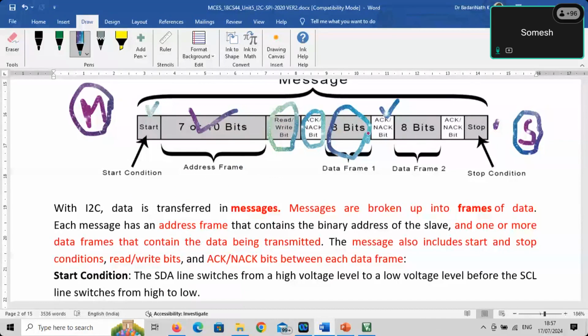So this is about the features of I2C. We have understood that I2C is from Philips. It has 2 lines, SDA and SCL. Both should be pulled high. It is a multi-master, multi-slave mode. A 7-bit address identifies the slaves. Initiation of communication starts from the master, and the master always generates the clock. The I2C protocol works at 100 to 200 kilohertz. We don't have a program in the syllabus, so I'm not required to read the registers either. Only how the I2C protocol works.